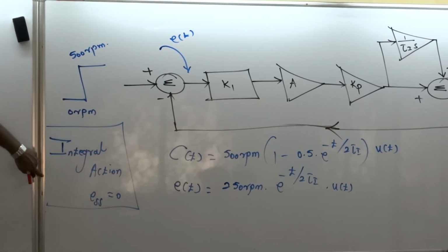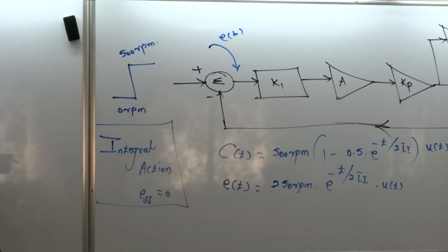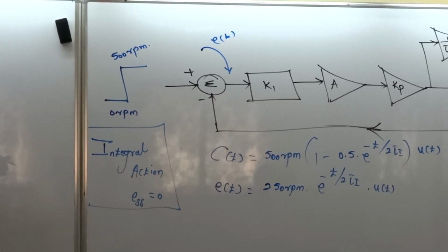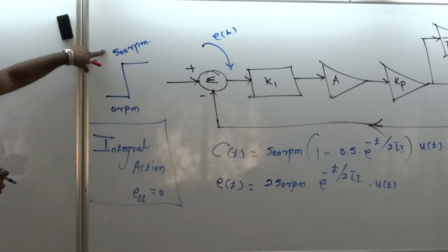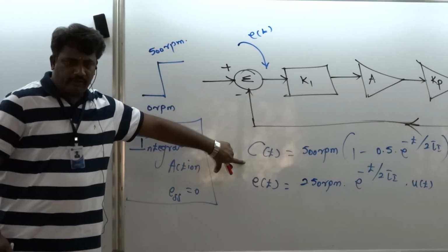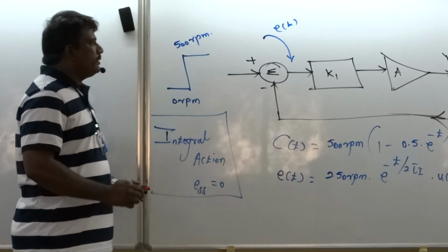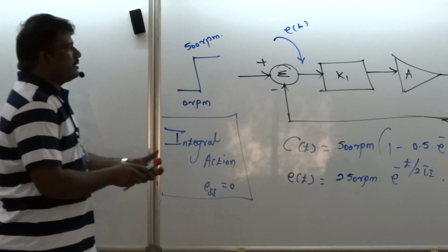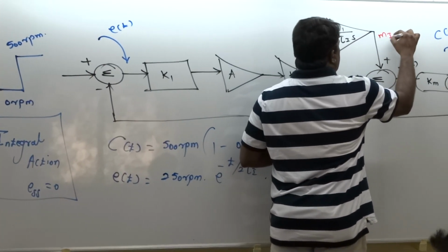That is what it was exactly doing in this loop, the PI controller loop, the closed loop control system to control the speed of the DC motor. The input command is 500, exactly the output response is equal to 500, so error will naturally go to 0.